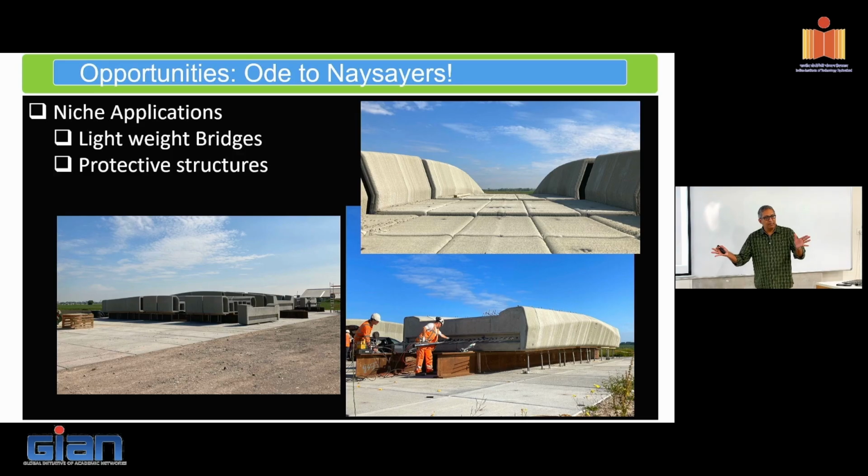So basically, each of these elements is brought together. Each element is about 1 meter in length. You stitch them together by applying post-tensioning to it. And so this is a very smart way in which I can use this.